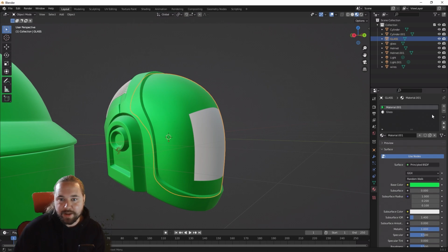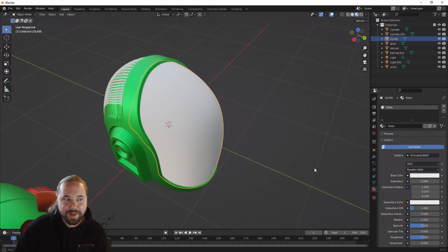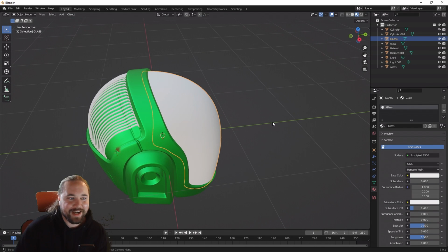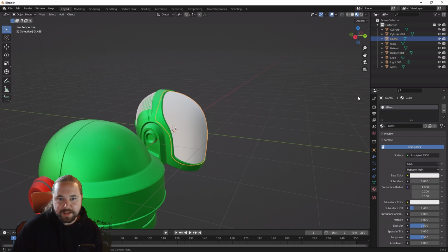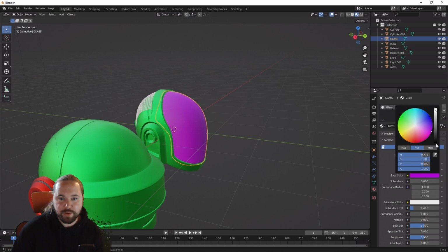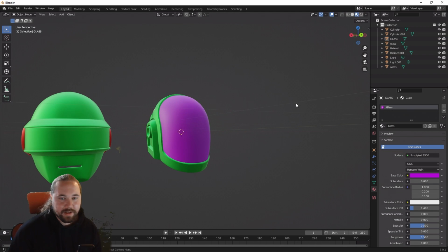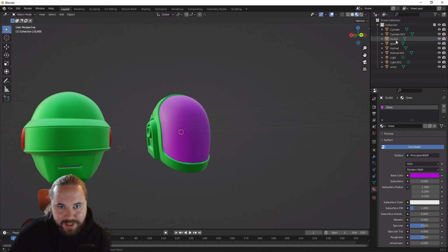So I could also just throw out the other material, and that will make sure this is the only material applied to this part of the geometry. So that's fine. I still want to give it a distinctive color, nothing to do with what it's going to look like later. It's just for me to easily see where I've already worked on the material and where not.